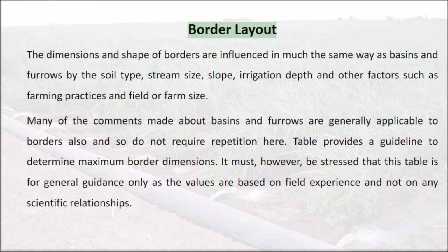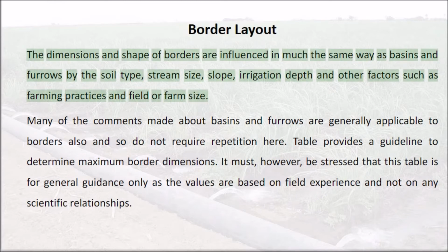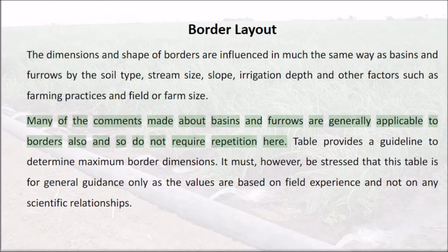Border layout. The dimensions and shape of borders are influenced in much the same way as basins and furrows by the soil type, stream size, slope, irrigation depth, and other factors such as farming practices and field or farm size. Many of the comments made about basins and furrows are generally applicable to borders also and so do not require repetition here.